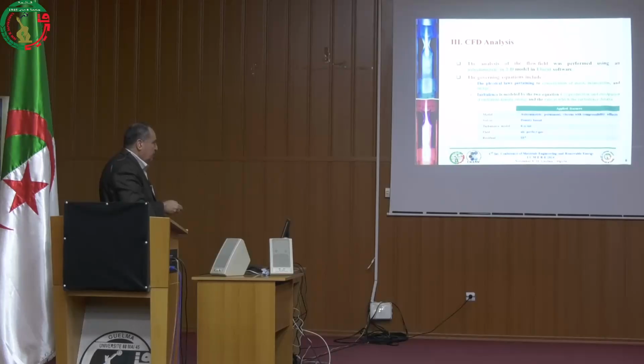We have used axisymmetric, steady, viscous flow with compressibility effects, density based. We have used air, just for simulation, as a perfect gas, and we have used a residual sensitivity of 10⁻⁶, which is quite a good number.